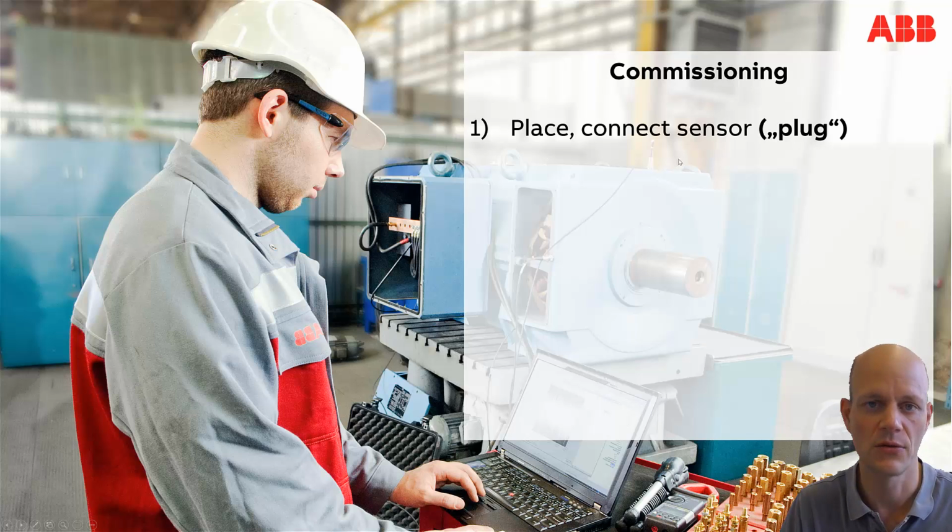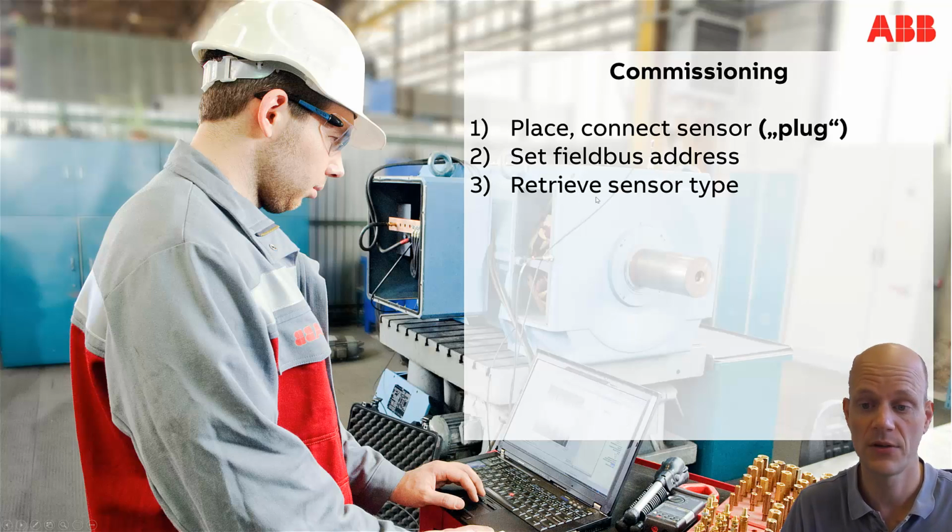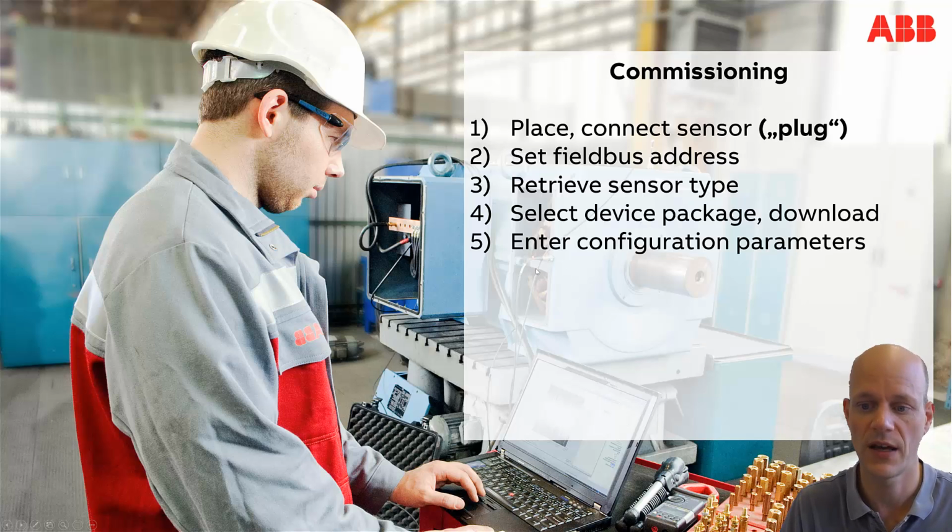Then you have to connect it to power and also to the network. Afterwards, you have to set some field bus addresses, retrieve the sensor type that you are looking at through your laptop. Then you have to select a device package, download that device package, enter some configuration parameters to really configure the device in a specific context.